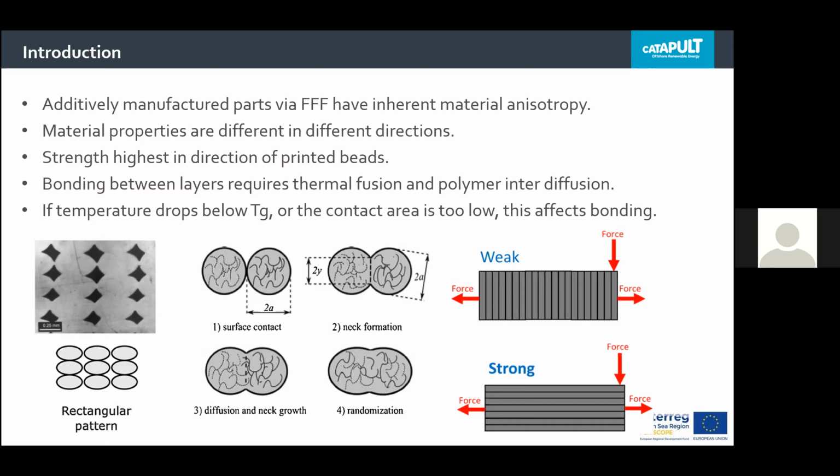So effectively, if you're printing something that's got too much energy, too much heat, too much thermal energy, if the beads retain too much heat, you effectively have lower viscosity, and the part will start to droop, or you won't be able to maintain good geometric tolerancing.